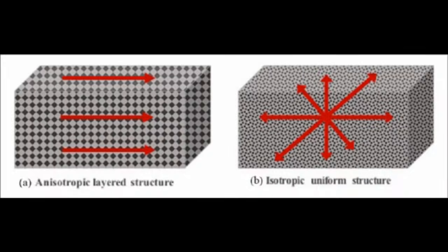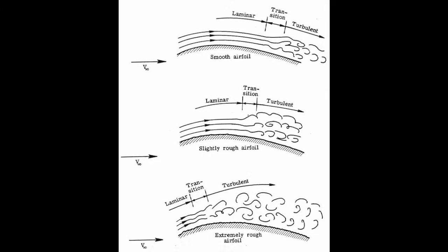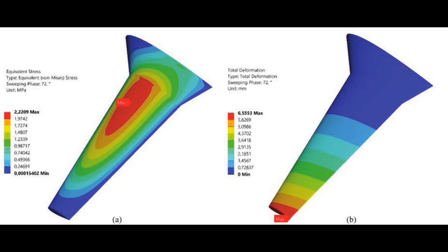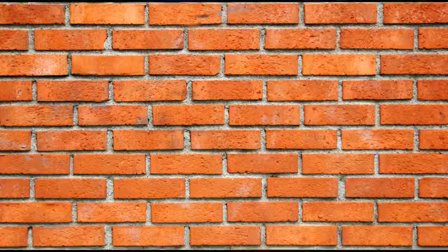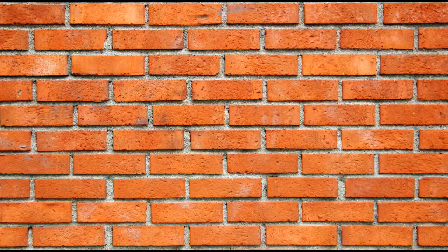However, I do also have more concrete reasons I dislike stair stepping. It weakens the parts along certain directions and causes rough surface textures that hinder aerodynamics. To give a combined example, an airfoil needs to be both aerodynamic and able to experience triaxial stress. A regular 3D printed stair step geometry fails to deliver on both counts. A non-planar approach would help significantly with the stair stepping and could even be used to better handle the stresses by better managing the layers, essentially like alternating bricks rather than aligning them.